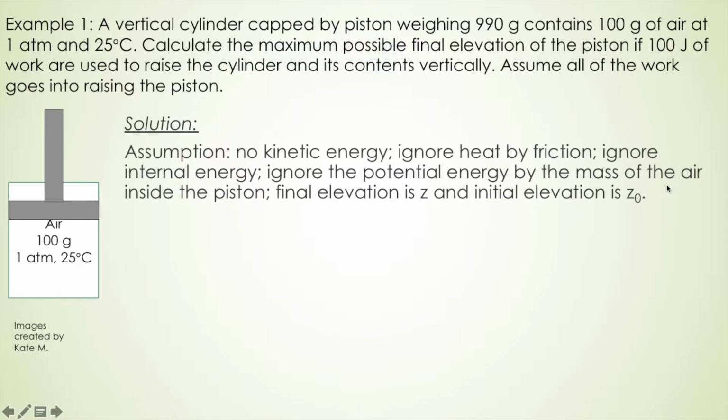And also, the air is a gas phase. It's difficult to measure the elevation of the gas phase because the molecules will be everywhere, filling the cylinder. So it will make things complicated to calculate the potential energy of the gas. And also, comparing the mass of the air with the mass of the piston, the potential energy caused by the air is a lot smaller than the piston's potential energy. So I just ignore the potential energy caused by the air inside the piston.